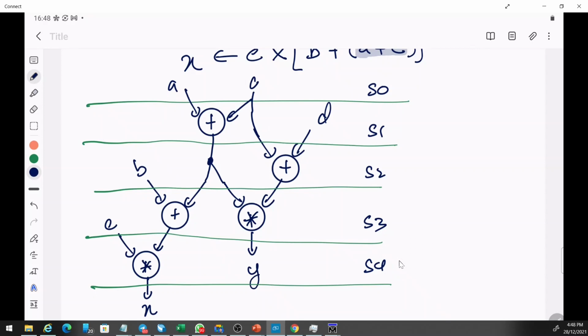The good thing is that you only add one cycle, yeah, the speed is a little bit lower as compared to the previous one, but only 1 cycle lower. But in terms of cost, which is very important in design, right? You now can reduce from 3 adders to 1 adder, right? So you reduce the cost a lot.